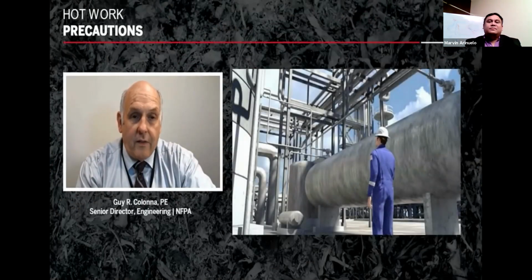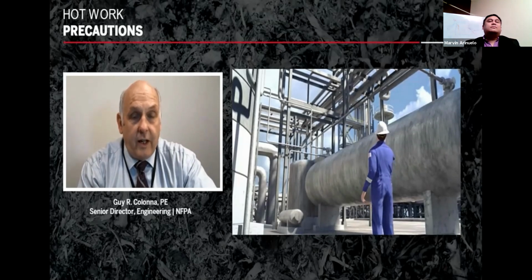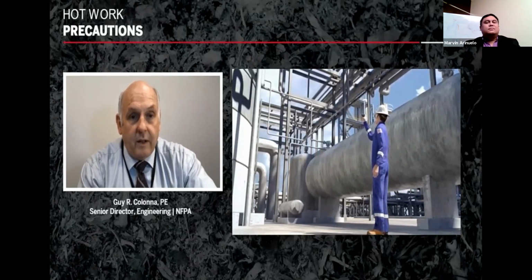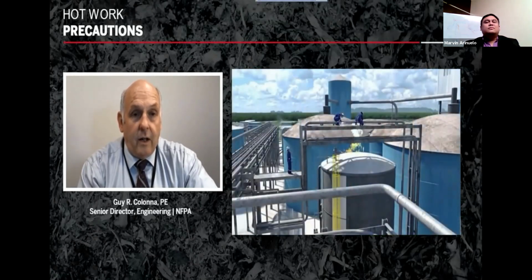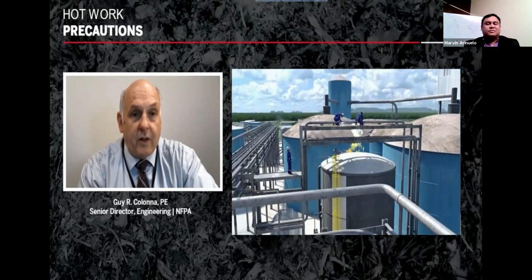Having watched this video, one of the things that we see highlighted from this video in terms of hot work best practices is that the company, in preparation for the hot work that they needed to have accomplished that day, involved atmospheric hazards. And so they did atmospheric monitoring in the area as part of their preparation and their documentation for issuing the permit. One aspect with respect to atmospheric hazards is that they are changeable. There is potential that the concentrations don't stay the same throughout the course of the work, and so it is better practice perhaps to consider continuous monitoring of atmospheric hazards.